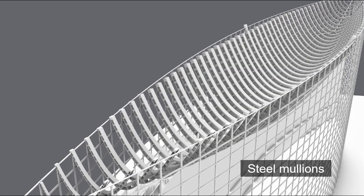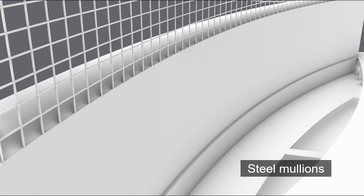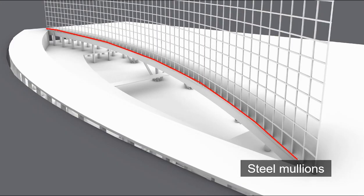At the top and bottom of each mullion are steel plates which anchor the unit to different parts of the building, either to the roof structure, the conference hall core, or the first floor concrete wall, depending on their location. This anchoring plays a crucial role in load transfer.